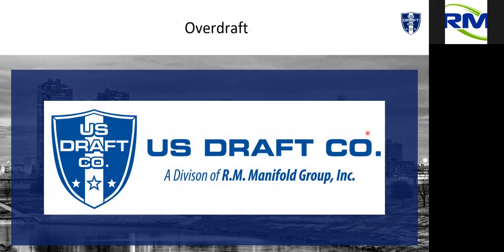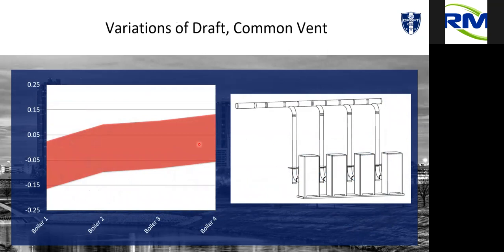Now, what about the other side? So we showed you where we needed draft on the high side here, right? But what about overdrafting? What if we're getting too much natural draft? That typically will happen in the wintertime, where there's a huge variance in temperature, although I think Southern California doesn't have a winter. But in the evenings, when it gets cooler, or when the entire system has been running and now we're on the backside where the boilers start to taper off, there's less volume, but that stack is primed so much that you're going to have some excess draft coming out of that. And that's where we come into overdraft controls.